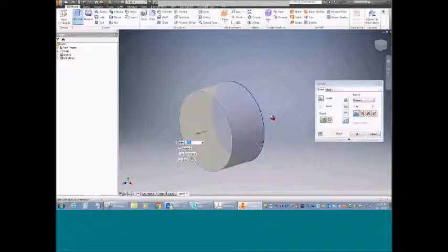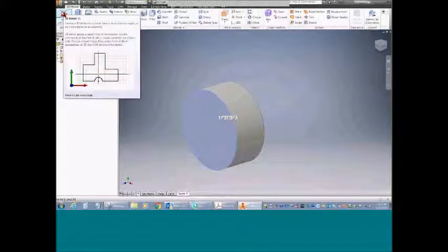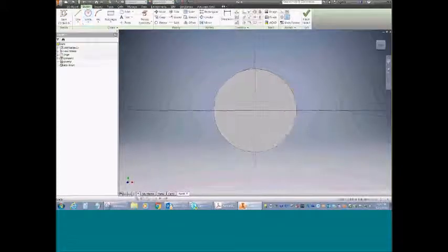Then we're going to extrude that 0.875 there. So I'm going to select this surface. I'm going to start a new sketch. Again, I kind of have my commands follow my mouse. I could come up here and select 2D sketch, or it's just right here as a symbol, so I don't have to move my mouse nearly as much.